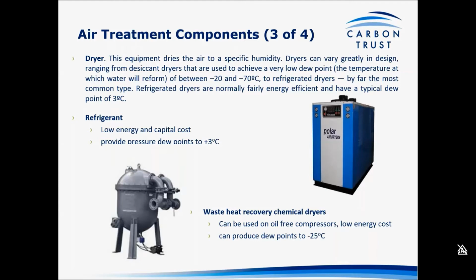They can vary in terms of their design and in terms of the dew point temperatures that they are going to achieve. Again, it's important to ensure that you're only treating the air to as much as you require in the process. The less treatment that you perform on the air, then the less expensive that's going to be. The most common are the refrigerated dryers, and if they're well maintained, they're actually very efficient and relatively cheap. The larger systems would use the chemical dryers.